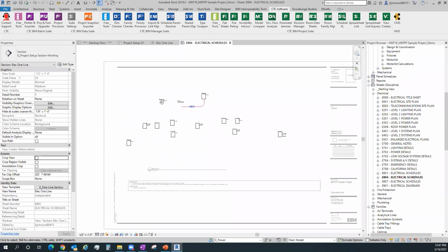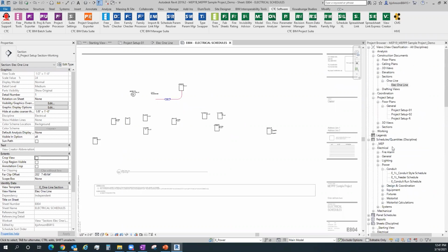Is there an easy way to draw parallel lines out of one device to another? Because those are conduits, I should be able to draw parallel conduits, right? So if there were, say, 6 of them that are all coming out together, I would just use my conduit tool, hit parallel, and say go, and it should do that. I believe that's always oriented to the view that you're in as well. Let me think about that one for a moment.